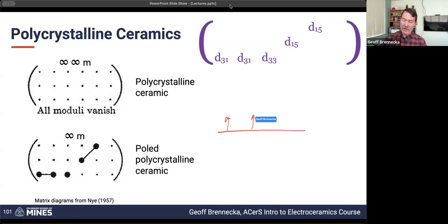So we're still nowhere near a ceramic aluminum nitride based piezoelectric. But the reason that we can use aluminum nitride based piezoelectric thin films in our resonators and cell phones is because when we grow the thin films, we can grow all of the grains pointing in the same direction. So that is essentially equivalent to poling the material.